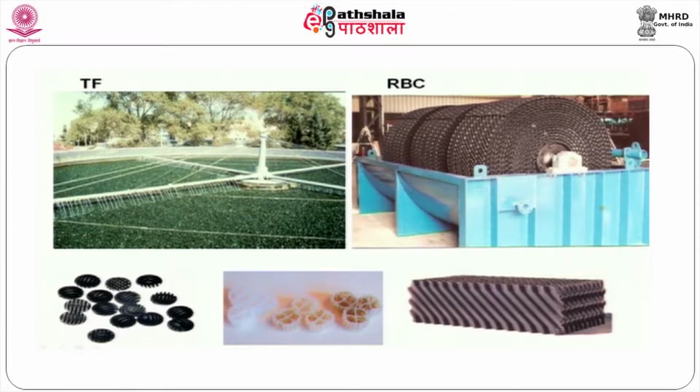This is the rotating biological contactor. 40 to 60% of the media surface is immersed in water. The rest of the media surface is exposed to atmospheric air. When the media surface is exposed to atmospheric air, atmospheric oxygen tries to diffuse into the liquid film, then into the biological film. When the same surface is again immersed in water, whatever oxygen was transported while the surface was exposed to atmospheric air will be released into the bulk fluid. So, in this way the system is continuously aerated.